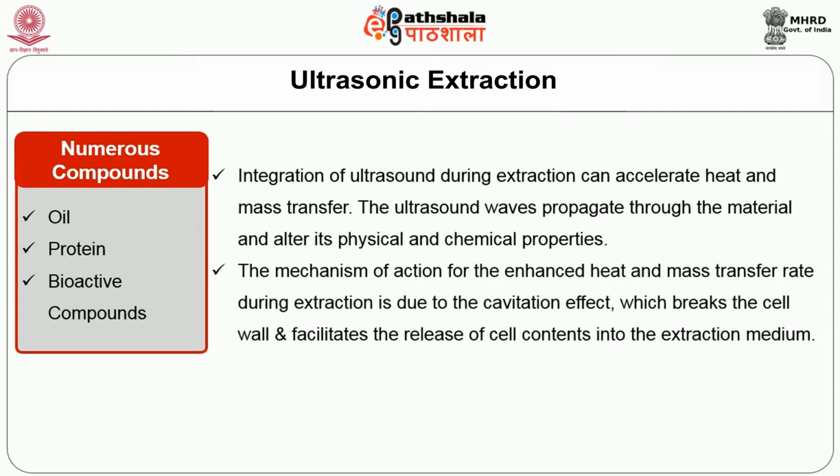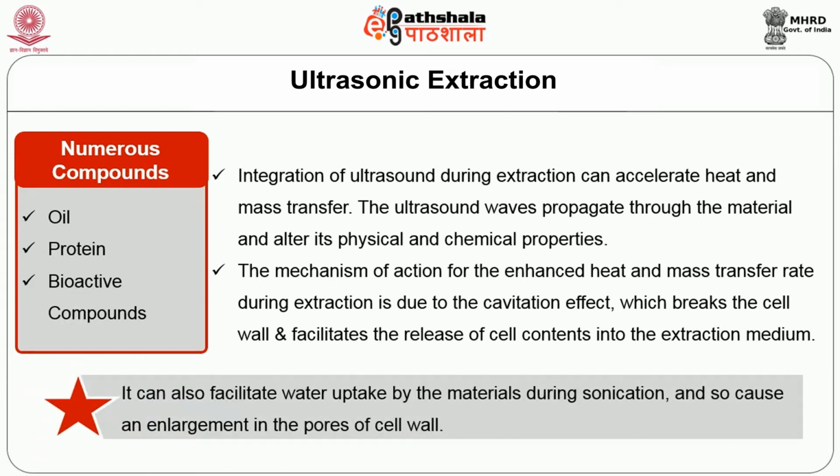The mechanism of action for the enhanced heat and mass transfer rate during extraction is due to the cavitation effect, which breaks the cell wall and facilitates the release of cell content into the extraction medium. It can also facilitate water uptake by the material during sonication, causing an enlargement in the pores of the cell wall.